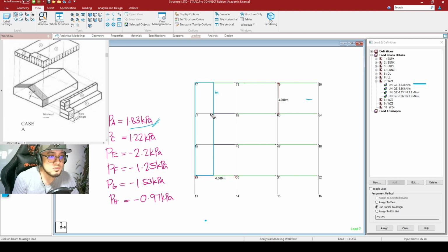So for us to determine the line loads here, that is basically the pressure times the tributary width. And we have already defined them earlier, that the tributary width of this beam right here is to be 1.5 plus 1.5, so that is basically 3. So same is true with this second floor beam. So this is to be 1.5, 1.5, and this is to be 1.5, and this is also 1.5.